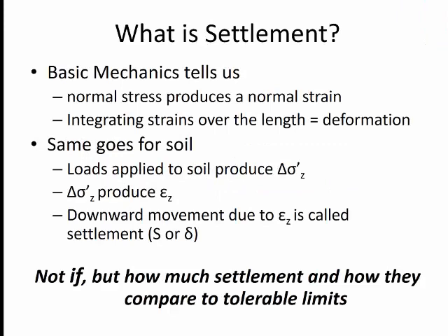And so let's go ahead and back up a little bit and say, what is settlement? Settlement is a term that we can probably understand from a conceptual perspective of something that is settling or reducing in size. But from a soil mechanics perspective, it really is similar to what we've learned in basic mechanics. It says that when we have an elastic type material, or it doesn't even have to be an elastic material, but most of the time when a stress is produced on some sort of material, that produces a strain.